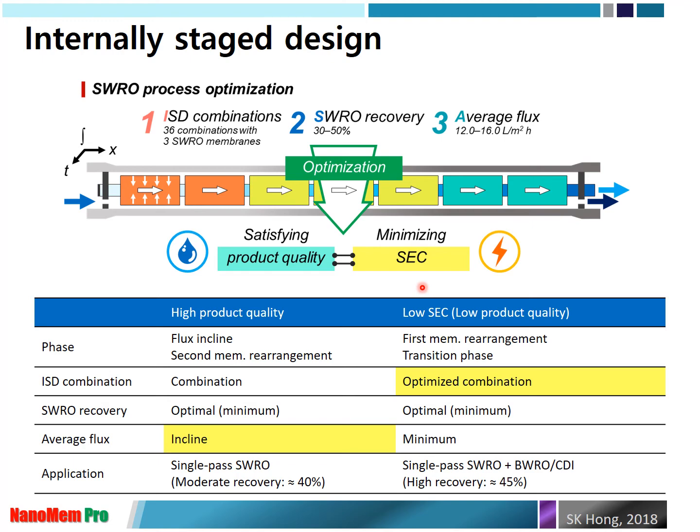So if you see this front part, there is a lot of fouling water coming through this membrane, and therefore we utilize the very high rejection RO membrane module, and then most of the organics and contaminants will be absorbed in these two modules. Then there is less rejection in the RO module, the most relaxed rejection, which means the high water flux can be allocated in this module. So they have different rejection and permeability, so that we can allocate them to different locations and produce better quality of water as well as lower energy consumption.